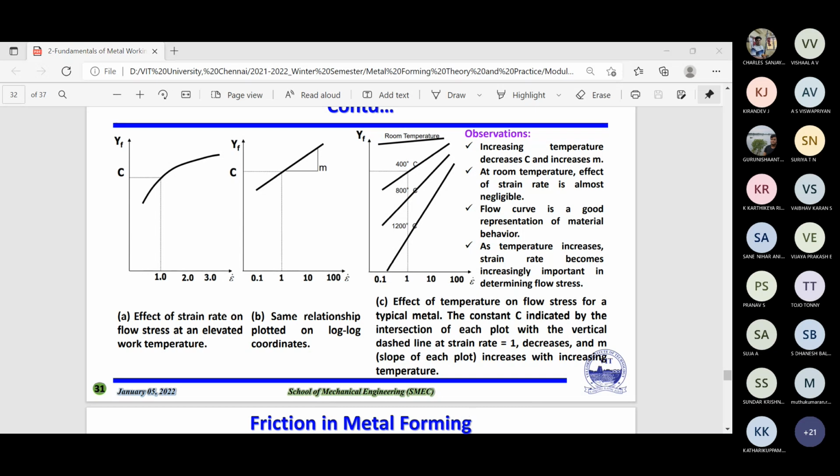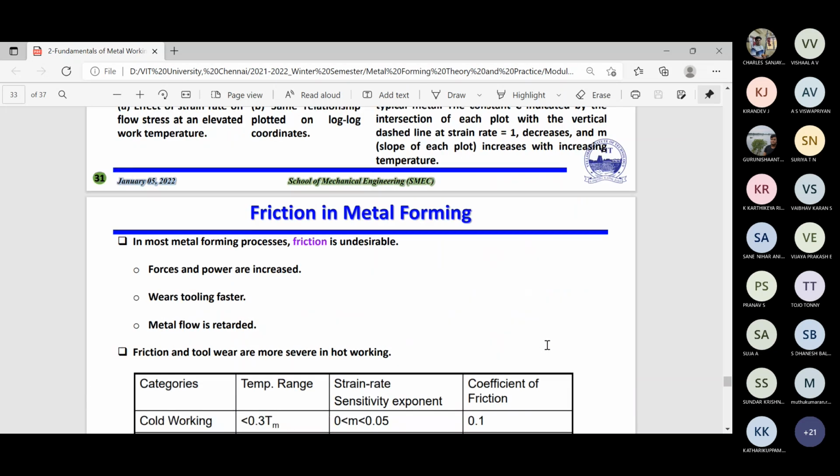What is the question it is written? In the question it is written, determine the mean flow stress that the metal experiences if it is subjected to a stress that is equal to its strength coefficient. So if it is equal to the strength coefficient, how much will be the strain? Epsilon is 1. Yes, sir. So you can use 1. That's why I repeated when I was explaining: if the flow stress equals the strength coefficient, then what will be the epsilon? So now you can use 1.